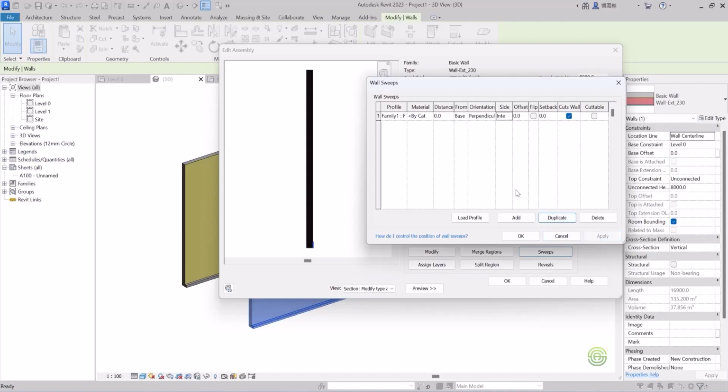Just click on apply. If you want to add a cornice on the interior wall, then again click on add a new layer and then change this to top. And now click on apply. So now it is on the top surface like this. So change this to interior, and the distance should be around -100 so that it will be properly located, and just click on apply. So it is not -100, so we have to give around -150 I think. Now let's apply.